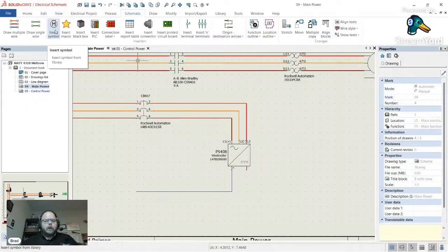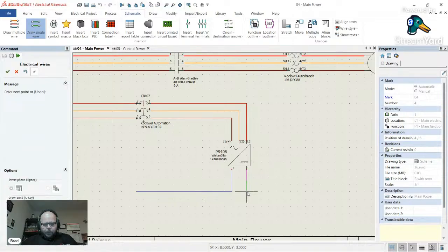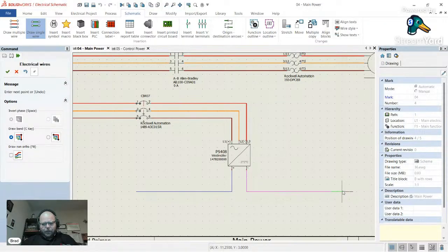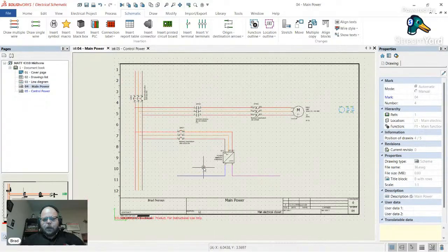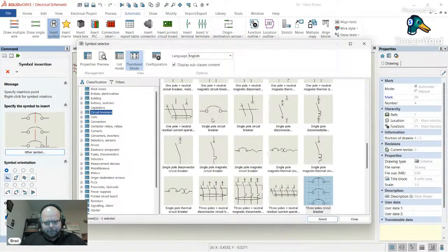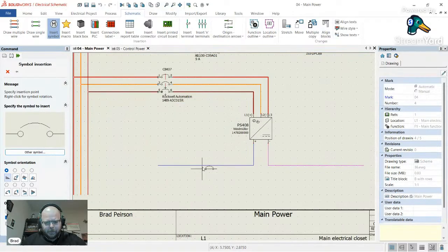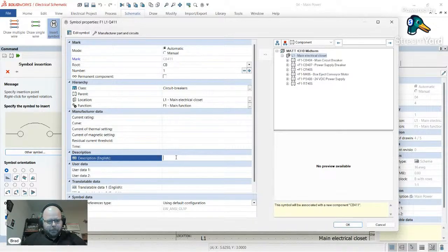Then let's draw the other wire while I'm in here. That's kind of cool. I've never done it that way as a subset of another way. It's always been its own thing when I've done that. So we got main power, we got disconnect, we got motor protected, we got power supply and protected. We need a single pole circuit breaker right there. There's a symbol for it. Drop that guy in here. Again, CB. And this is going to be the 24-volt DC breaker.